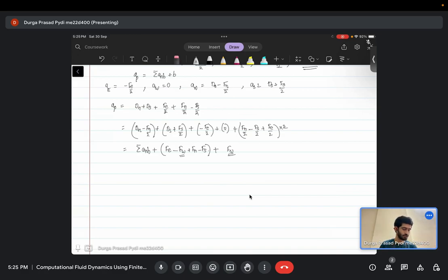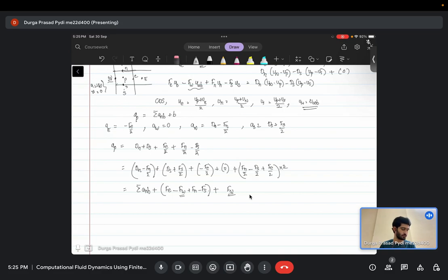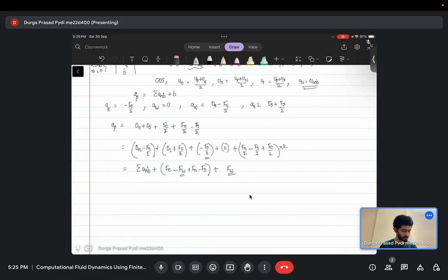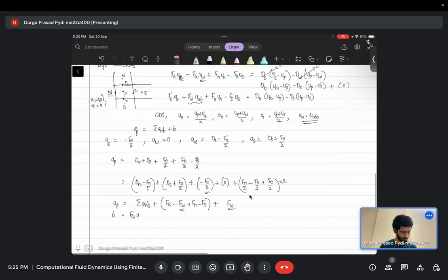So when we write the coefficients here we have a Dirichlet boundary condition. In the case of a Dirichlet boundary condition, in this particular scenario it is on the u and our d is 0, so we don't have any term adding because of diffusion in your A and B term. Otherwise you will have one more additional term coming up here in the east coefficient, which is not present here right now. We'll get to see that as well in the coming example. So this is your AP, and previously we did not have a B term, but now we have a B term that is essentially coming from the west boundary, FW. So this is your B term. So this is for the left boundary.